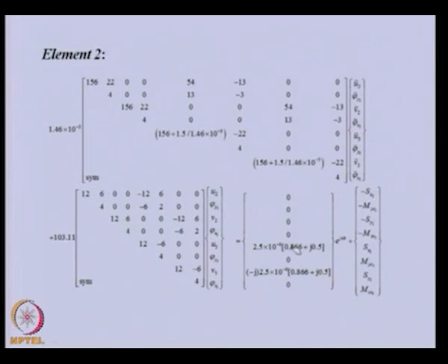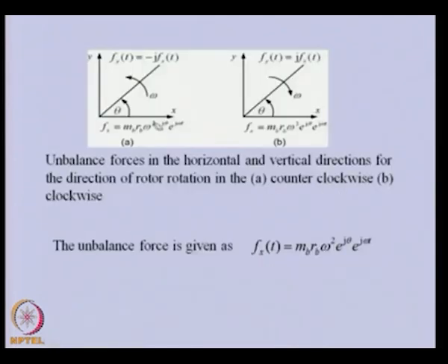And this is the phase which we were talking about initially, that is the 30 degree phase which we have considered. And this is the case when the shaft rotation is in the other direction. So in this particular case, the y axis will be leading the x axis by 90 degrees. So the force components in the y direction and x direction will be related by this. So instead of minus j, now only j will be there. So we have considered this particular case.